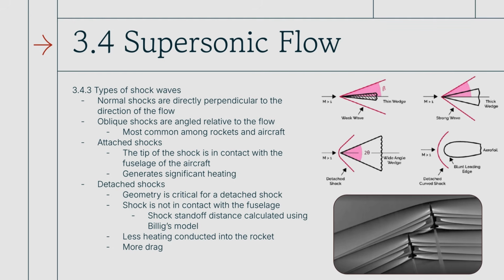So, for example, on our rocket, we actually round the tip of our fins because we don't want the fins to experience a lot of heating, because if they did, then the epoxy would melt, the carbon fiber would fly off, and your fins are no longer fins, and your rocket is no longer flying. We purposely round them to force the shock structure to be detached. But it really depends on your design conditions. Like our nose cone, we just make it out of steel, and then the shockwave is attached, right? And so that's beneficial because you have a lot less drag.